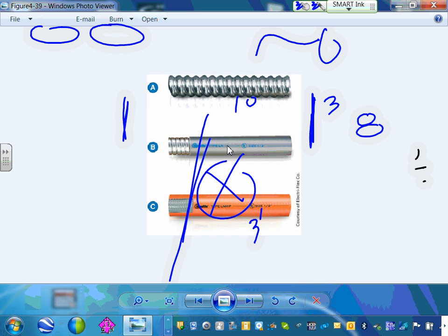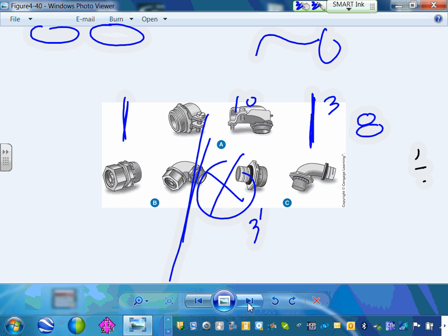Here's different types of cables. Flexible metallic conduit, this is only approved for dry location. Now what happens if you have it on a roof? Like in Minnesota, they put a jacket over it to protect it from the elements. It becomes like this. If you put the plain one in a wet location, this does not qualify. This is dry only. Then you have to use watertight flexible metallic conduit or non-metallic conduit.